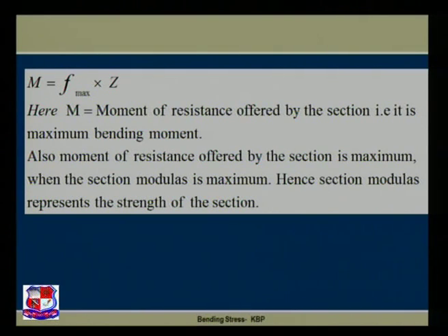Also we have studied the strength of section. M is nothing but the moment of resistance offered by the section. The moment of resistance offered by the section is maximum when the section modulus is maximum, hence the section modulus represents the strength of section.